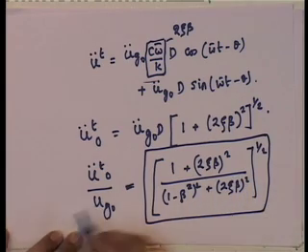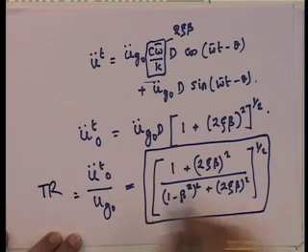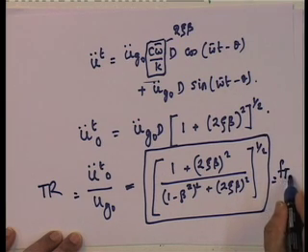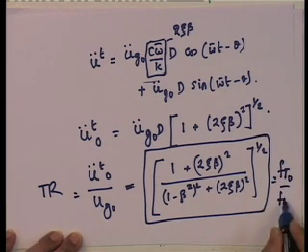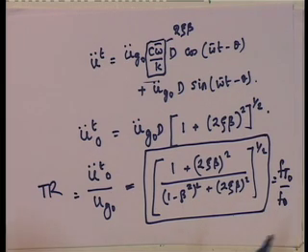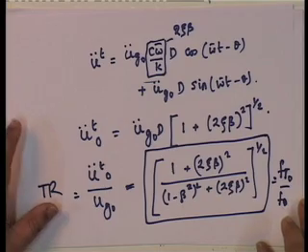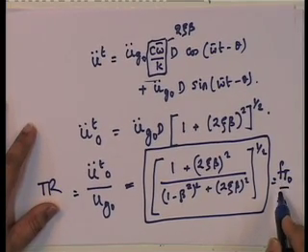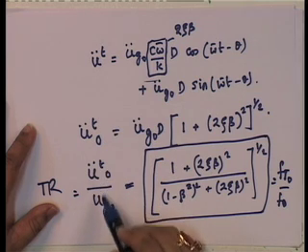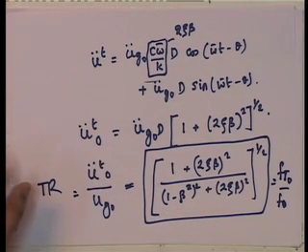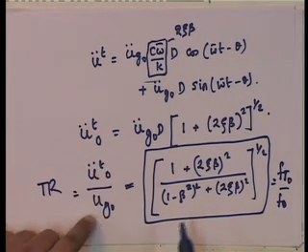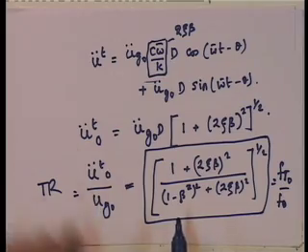What is this? This is the same as the transmissibility ratio, which was f t 0 upon f 0. Two totally dissimilar problems, absolutely dissimilar problems. One is a force transmissibility problem, the other is transmission of base acceleration to the equipment acceleration. So, this is a base isolation problem. We are trying to isolate the base vibration from transferring on to the equipment or whatever, I am calling it equipment for want of anything else.